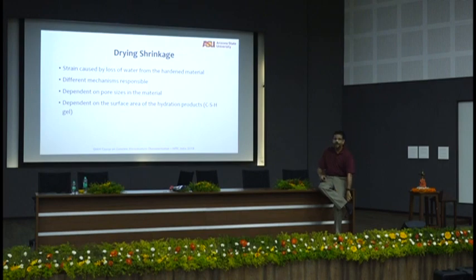Okay. Now, shrinkage is a strain. First thing to remember, shrinkage is a change in volume. When I say shrinkage, it is not a stress. Shrinkage is always a strain. The stress happens because of the effect of restraint. Because you are holding on to it and you are not letting this volume change happen. The beam wants to shrink, but you have held the beam in place with the columns, told the beam not to shrink, so it creates internal stresses, right?